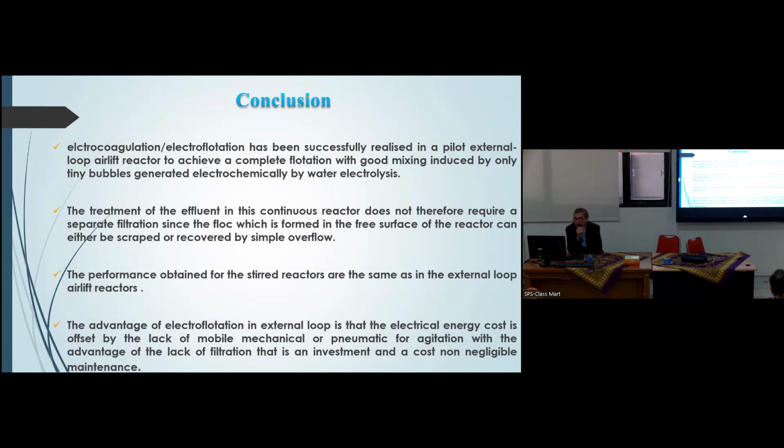The treatment of the effluent in this continuous reactor therefore doesn't require a separate filtration, because we can remove the flock, since the flock formed on the free surface of the reactor can either be scraped or recovered by simple overflow.